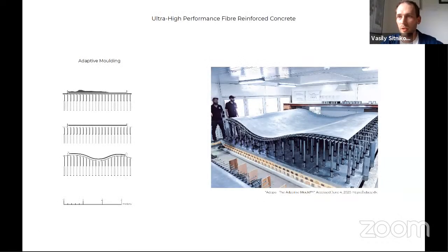And here we come to the concept of ultra-high performance concrete, which is capable of doing the same shell. However, its superior physical properties do not require the external steel reinforcement anymore. The concrete element can perform on its own, even though the thickness would be 2 or 4 centimeters for a giant facade element. However, the properties of this material in a fresh state required the development of new approaches to making the actual product. You cannot spray it anymore, because it is a self-compacting concrete. It requires flowability in order to make the dense structure.